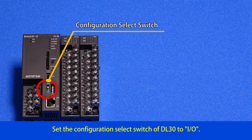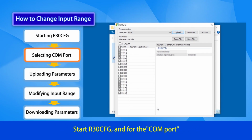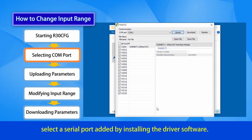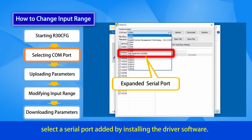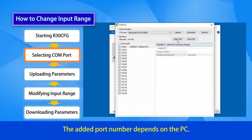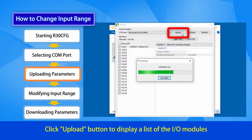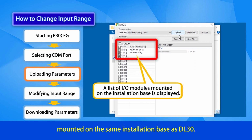Set the configuration select switch of DL30 to I/O. Start R30 CFG, and for the COM port, select a serial port added by installing the driver software. The added port number depends on the PC. Click Upload button to display a list of the I/O modules mounted on the same installation base as DL30.